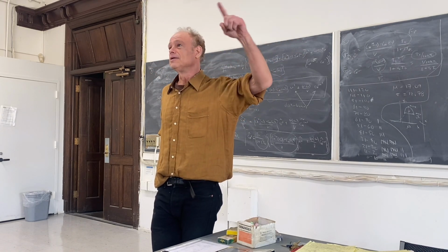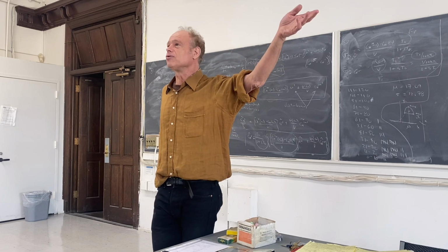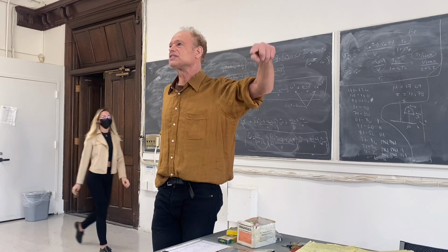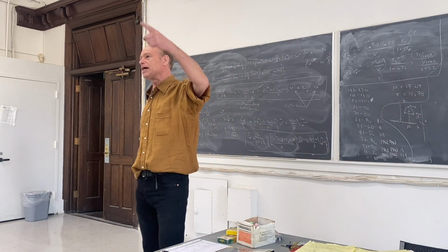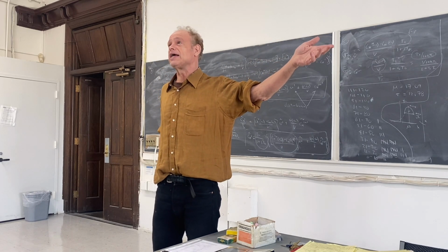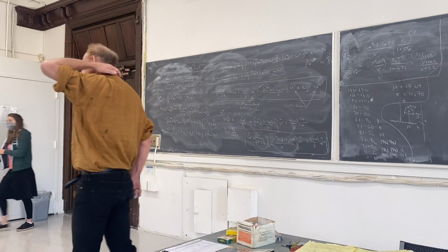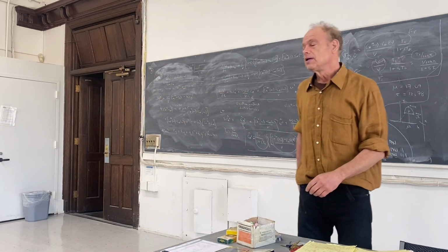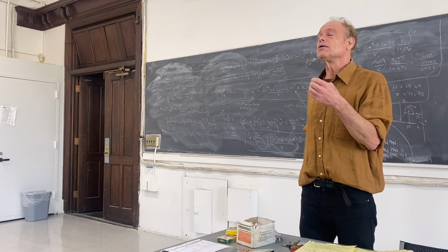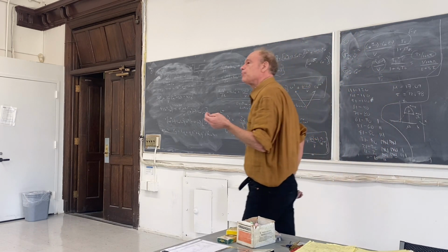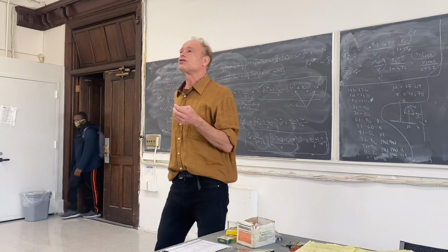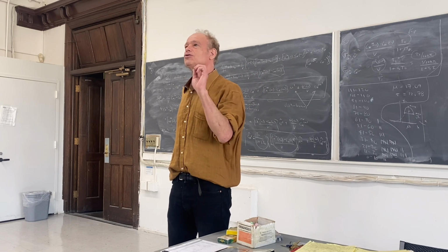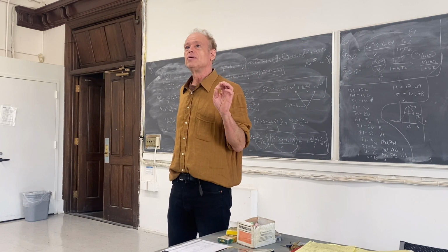You have an oscillatory temperature between day and night. It oscillates. You want to know, do I really have to put tons of insulation on everything, or is it not a problem? What happens if I have this oscillatory input of the temperature between day and night? What's the result? How does that affect what's going on? And as we'll see probably next class, but maybe I'll get to the beginning of that this class, you can determine whether things are going to blow up, whether things are going to oscillate. What is the response to a sinusoidal input? You can determine those things directly from the Laplace transform without inverting.